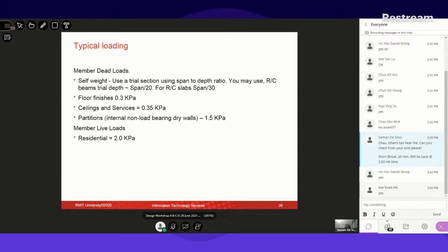Drywall construction really means we are not calculating its length, its height, and a line load like we do in brickwork, which is very heavy. What we normally do is we allow on the slab a uniformly distributed load to cater for partition walls. So all partition walls added together, divided to get the weight in kilonewtons, and then divided by the total area of the floor